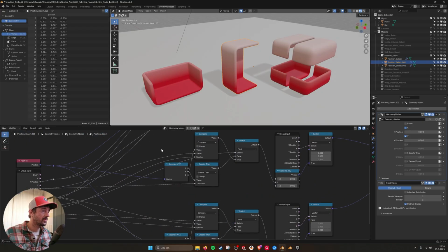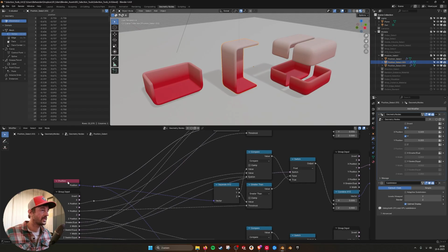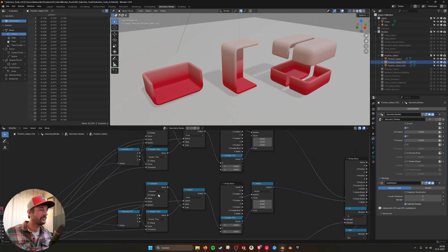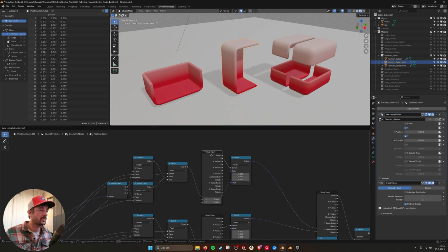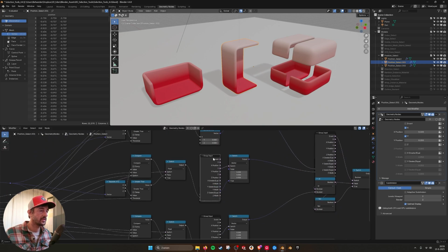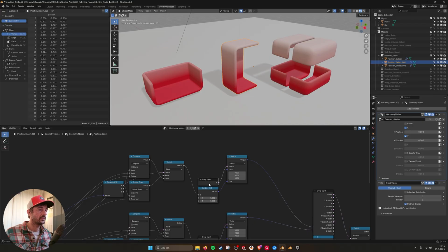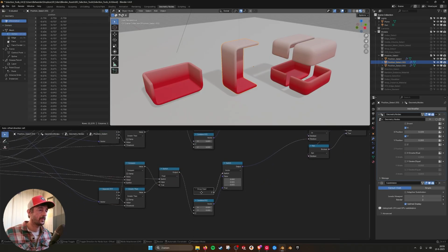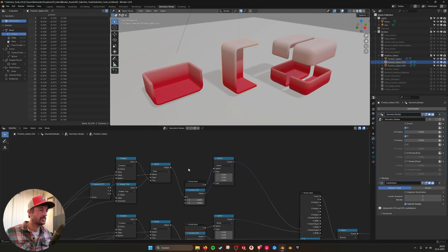It's again a little bit more complex, but I'm using compare nodes and then a greater than node with a separate XYZ, and that comes in from a position node. It's just everything below this is a copy. This needs a little bit more space, so you can see, or I hide it. I'm using just the Y. Here I'm using the X value, and here I'm using the Z. So then you know why these are split like this.